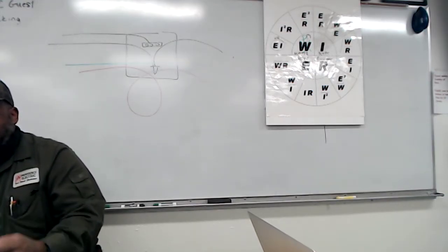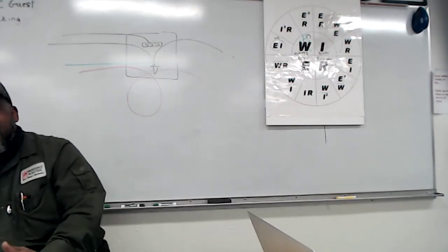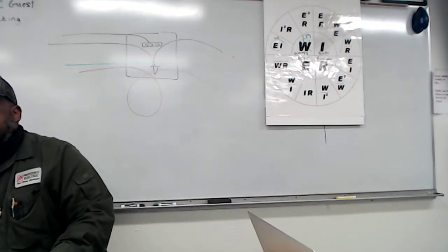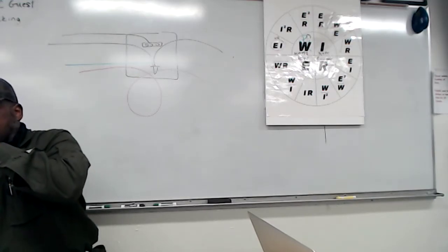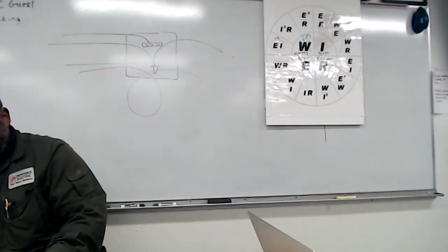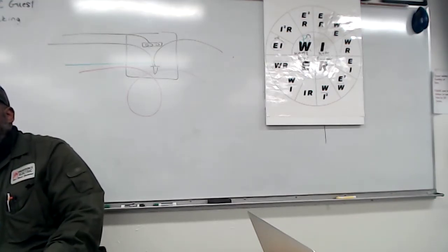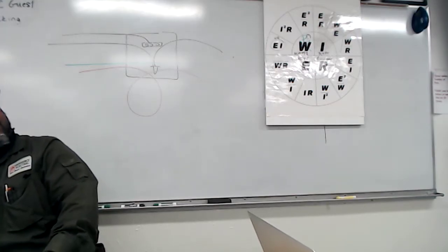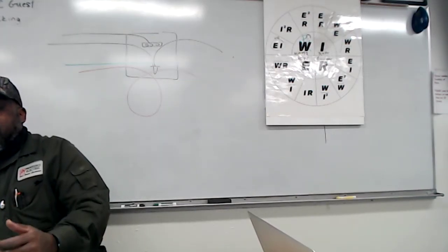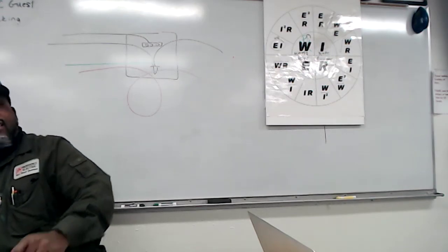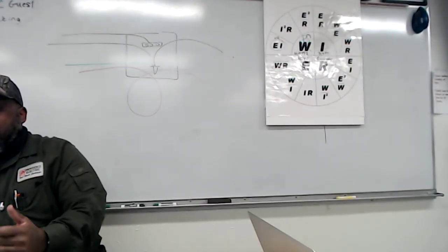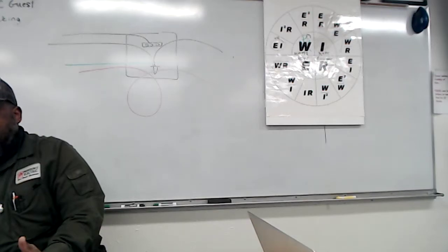Okay, so then you look at this question. I already have 1 receptacle based on the figure. I already got 1 receptacle in there, right? It says that I'm going to add another receptacle. And it looks like the biggest wire in that box is number 12. Both receptacles have number 12 wire in there. I take that back. There's a 10-2 in there too. So if I look at the 10-2, I'm going to count the neutral and hot as 1 allowance.